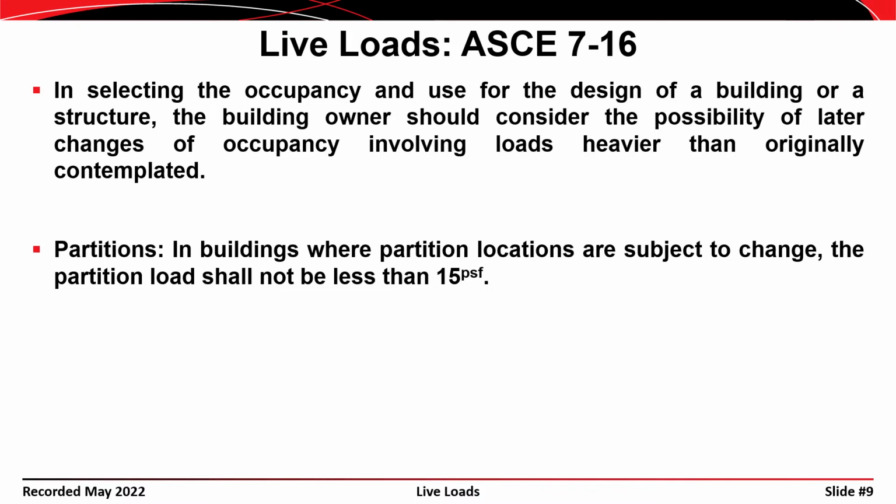But when we talk about partition loads that are live loads, then we're thinking about the type of partition wall that can be moved. So we're not talking about a load-bearing wall that has to be there, but just a wall that separates the bathroom from the office space, or maybe a wall that separates the supervisor's office from the general workers. So this is generally just gypsum board on metal studs or wooden studs, and it can be removed at any point and moved around.